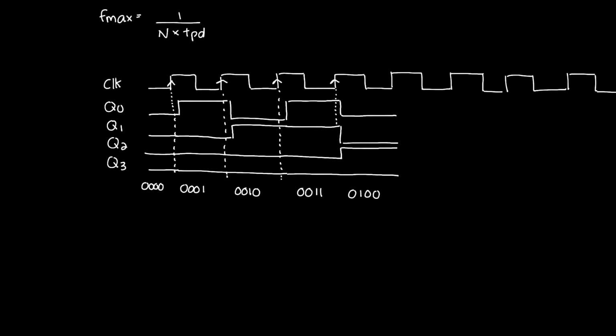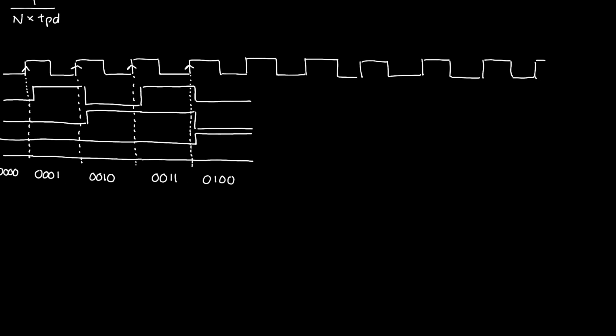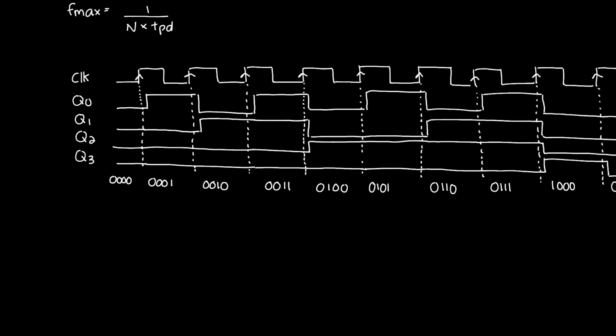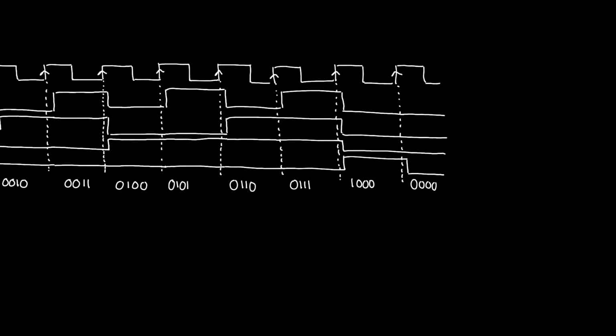And let's make that explicit here so I can see. Now, when I see all counter outputs toggling, or when I see the counter outputs that are toggling toggle at the same time, then that is a clear indication that what I'm looking at is a synchronous counter. So I'll continue doing this. So I've mercifully filled this out for you.